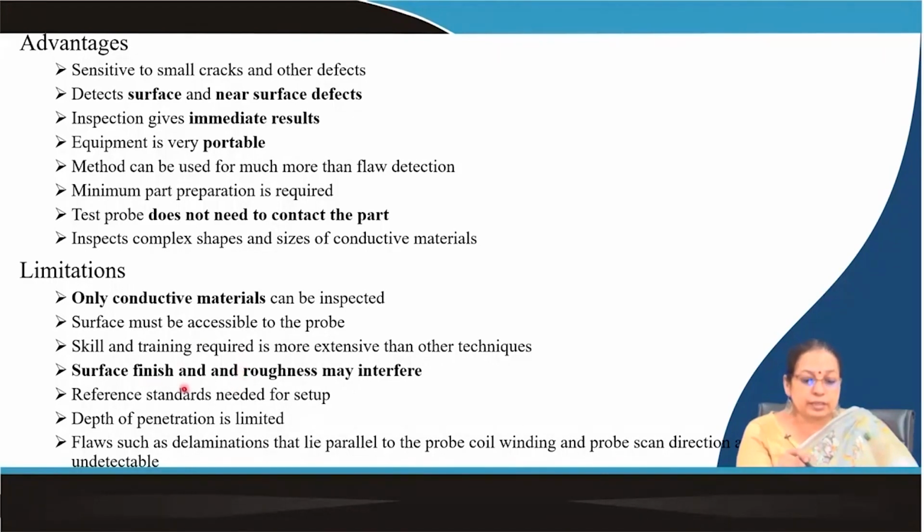Certainly, reference standards are needed, because unless you know how the current and the signals will be for whatever kind of defects, you will not be able to know. You have to model it and finally find out what kind of defects are there. And depth of penetration is limited. Flaws such as delaminations that lie parallel to the probe coil and probe scan direction are undetectable. So, you have to be very careful that not all kinds of flaws are detectable using